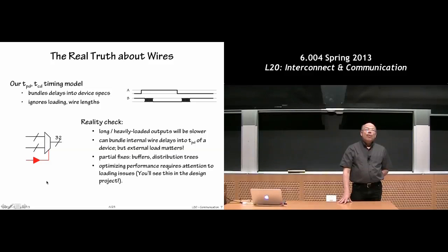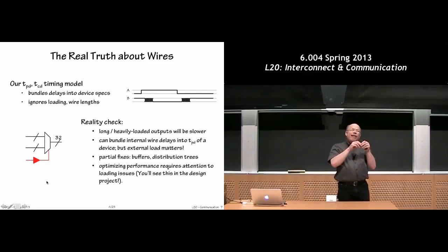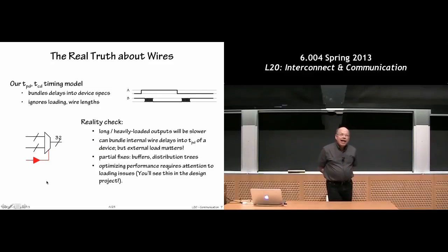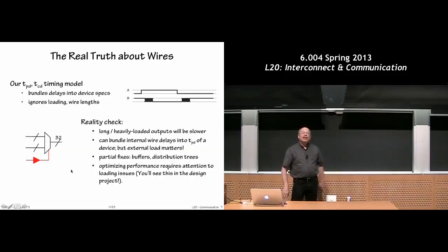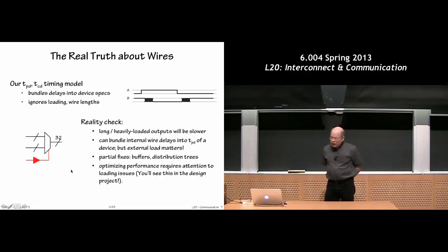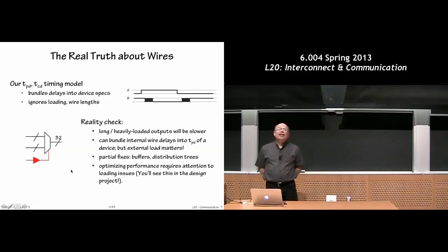And you could say, woo, it turns out that if I'm a bit careful about how I distribute signals, instead of having one signal go everywhere, suppose I made 5 copies of the signal and have them each go to 1/5 the number of places, that'll turn out to make your beta noticeably faster. In fact, you can make almost a factor of 2 difference in the clock speed of your beta by taking into account these issues about loading and carefully distributing signals such that no one signal has to do all the work.